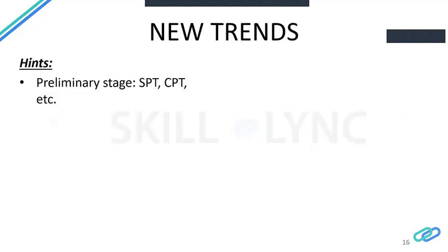Since when dealing with the finite element and the practical aspects of the foundation engineering system, we know that in most of the cases we receive soil reports with basic information like SPT, the standard penetration testing, or the CPT, the cone penetration testing. And you will develop the parameters of your model initially in codes, from those parameters, from the SPT or CPT and the like.